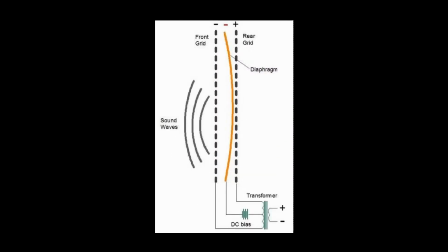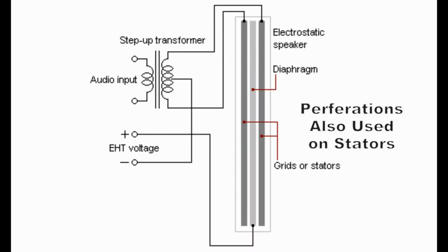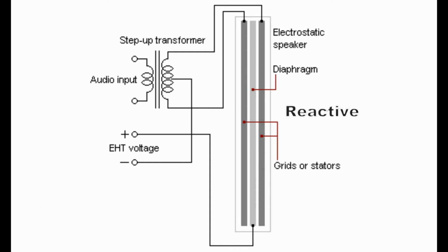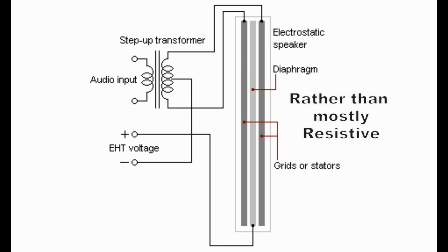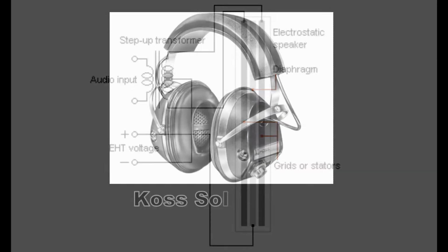Next, the biased condenser microphone was invented in 1916. This principle in reverse is the basis for the electrostatic headphone driver. Classic electrostatic drivers have an extremely thin membrane sandwiched between two electrified plates. With very little mass and suspended within an electrostatic field, this diaphragm moves with static attraction and repulsion to create the sound waves. The driver must be biased in order to keep the plate at a rest point slightly away from being attracted to the other plate. Without bias, the two plates would be attracted to each other and the whole thing would close.